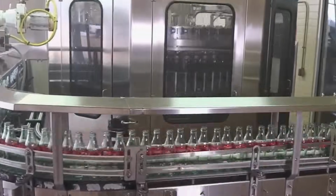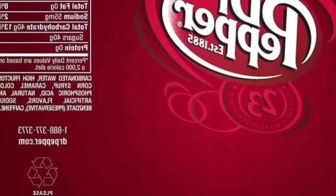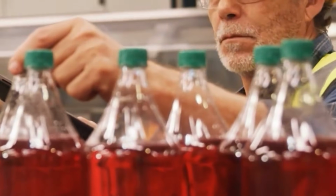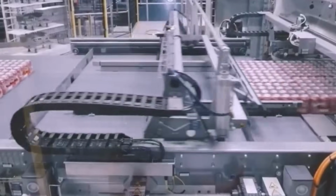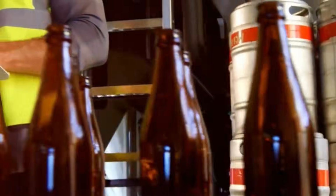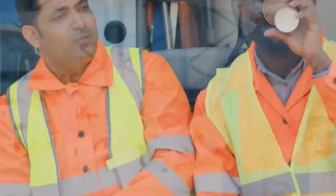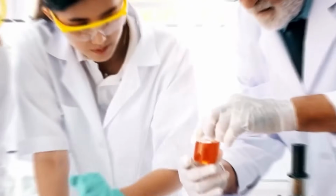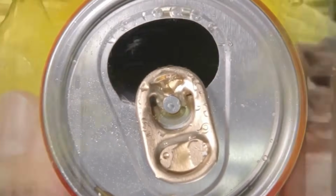Bottles pass through a label applicator fitted with servo-driven rollers. Pre-printed labels on adhesive rolls are cut and transferred using vacuum drums. Each label is wrapped and smoothed onto the bottle's surface using motorized brushes. Can lines use shrink sleeve applicators. Sleeves are dropped over the cans and pass through a heat tunnel where forced air heaters contract the film around the container body with uniform tension. Each labeled item is scanned by barcode readers to verify correct SKU association.